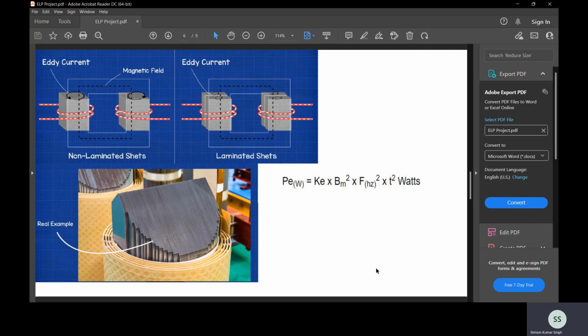So now we come to the core of the coil. The core of the coils is basically an iron core. This is done so that very little magnetic flux is lost to the surroundings. If we place a very solid core instead of the core used today, a lot of heat will be lost in the form of eddy current or the copper loss.